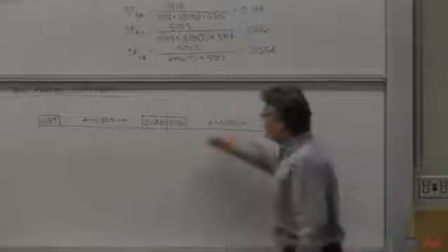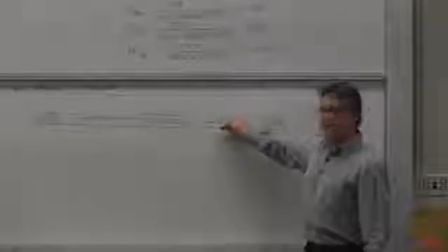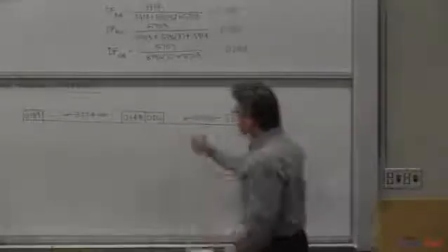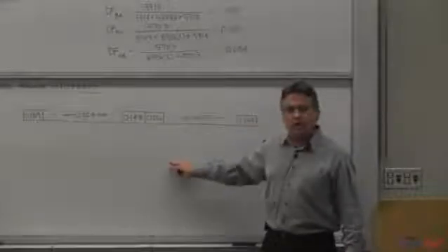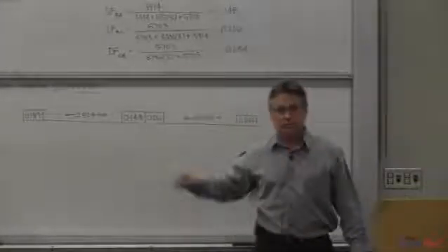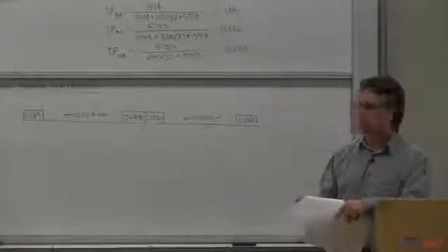Okay, I want you to get to here. Some of you will wait till a week before. There's nothing I can do about it. But I would like you to, this will not take long. You're going to have to calculate the section properties of the beam and the column. That should go quickly for you. Once you get the moment of inertia of the beam and the column, you can calculate the stiffness factors for the columns and for the beams, and you can quickly calculate what the distribution factors are.